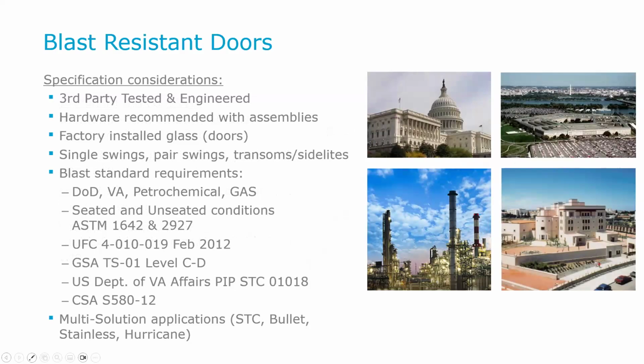Now, another thing, the last bullet point on the screen there, it talks about multi-solution applications. Over the last probably 5 to 8 years, our industry has seen a shift where not only does that project require, say, that opening to be blast, but they also want it to have an STC rating, a sound deadening, or they want it to be stainless and blast.